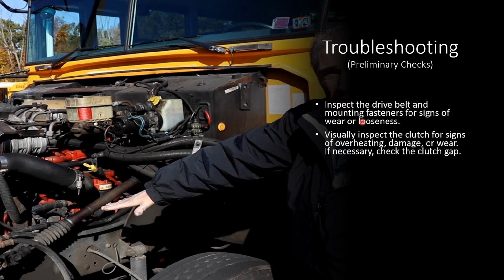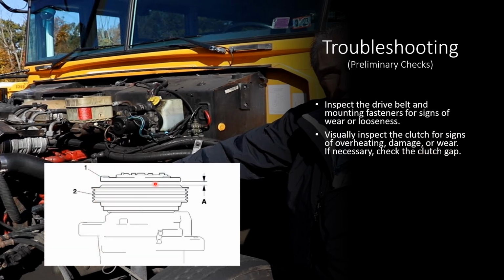So I'm going to do a visual inspection of the clutch, and I'm going to make sure that the gap is in good condition. A lot of technicians don't know what the gap is. The gap is going to be the gap between the clutch and the pulley. So here we have the pulley. This is where the belt rides on. This is looking at a clutch from the upward position.